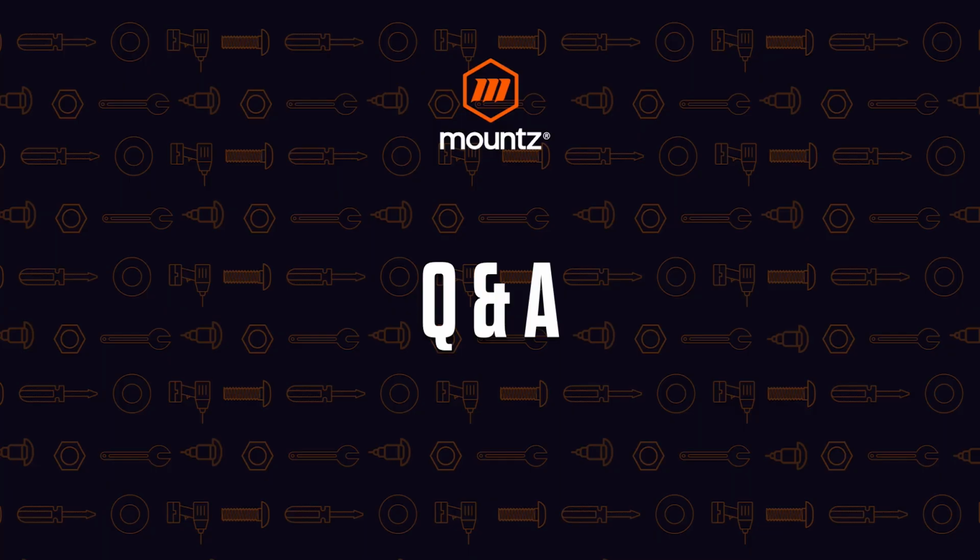All right, Dave. Another question we had was, for a fastener that's already been seated and torqued, is there a tool to analyze the actual applied torque to get it seated? So if we want to do any type of after the fastening type of auditing, that can be done through the use of a digital wrench that may have an auditing feature that you can use to measure at a certain degree of rotation by adding additional torque to, or you moving that fastener in the operating or tightening direction just a few degrees. You just want to get to anywhere from 3 to 10 degrees of movement and measure what that torque is.